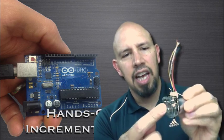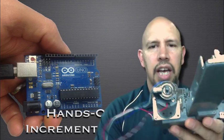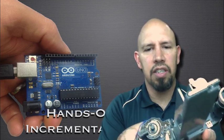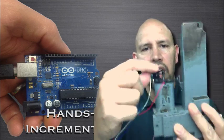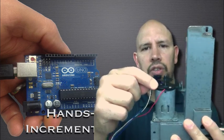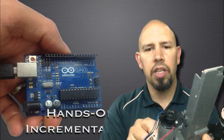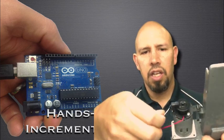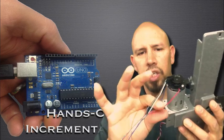Okay, this one is an optical encoder, and here you can actually see the stuff inside. And when it's running, you can actually see the LED lit. So a number of different options. Here is an encoder that is connected to a bunch of gears and stuff. You can see here's the optical disc, and here's the emitter and detector associated with that. This one in particular, notice that the encoder itself only has 3 wires, and it has 2 wires for the motor.